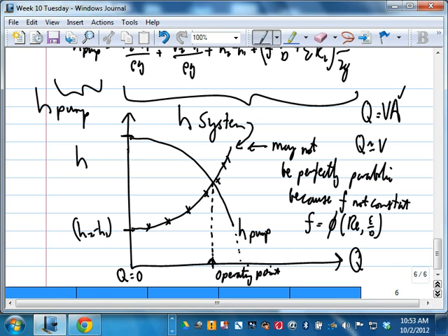Instead of doing any spiral, it just goes straight radially out, so you expect no head to be formed. These are the extremes: maximum spin, no spin, and in between, some spin and some radial movement. That's why the head curve looks like this.